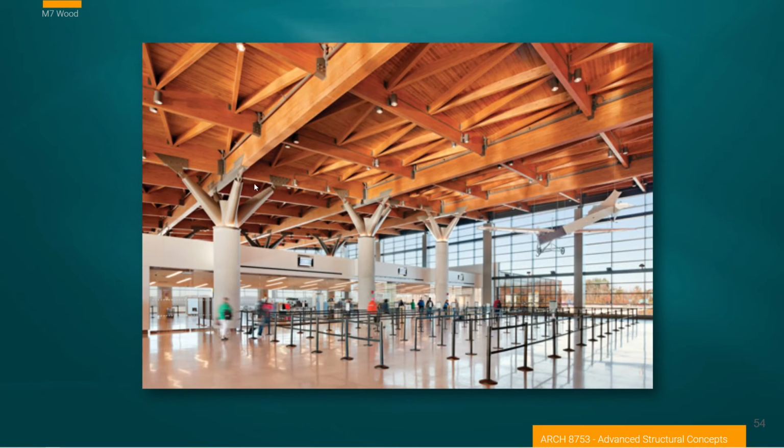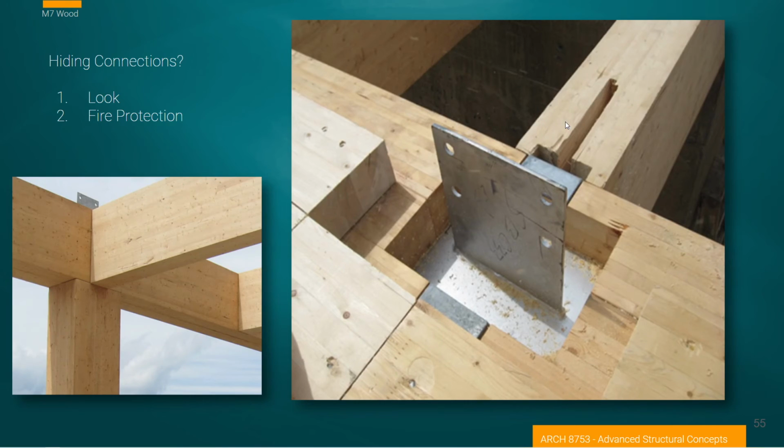So we've done adaptive columns that come out and distribute loads like this. So really, I think a nice way to deal with distributing these loads or carrying these loads back down to center column systems. And then once again, all of these, I guess, transfers from wood to steel of load path all become architectural elements in and of themselves. And once again, they're exposed, and they're probably exposed because it looks like we may also have a sprinkler system here, although these also could be drained, I'm not sure.